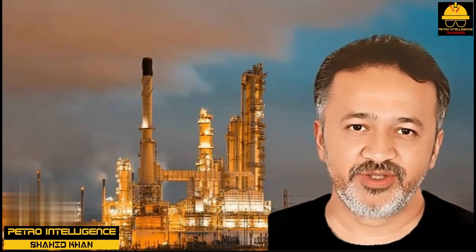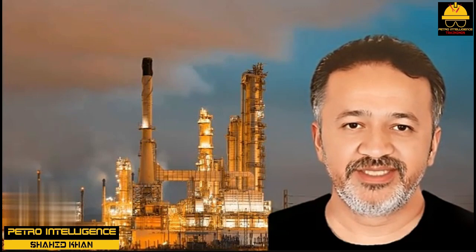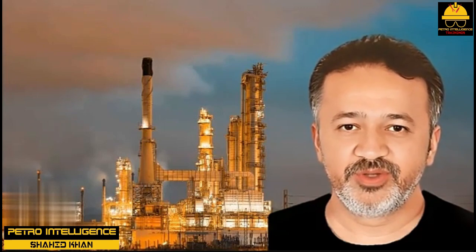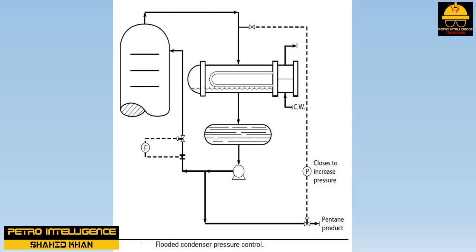However, assuming that we have plenty of condensing capacity and are operating well below the relief valve set pressure, why do we attempt to fix the tower pressure? Further, how do we know what pressure target to select? Let us have a look at this pentane-hexane splitter. The tower simply could not make a decent split, regardless of the feed or reflux rate selected.